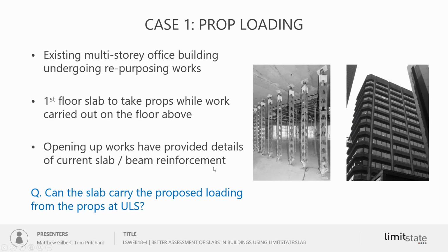So for the first case, we're looking at prop loading in an existing multi-storey office building which is undergoing some repurposing work, so of the type that you can see here on the right hand side. The first floor slab is to take some props while work is being carried out on the floor above, and opening up works have provided some details of the current slab and beam reinforcement so we can use them within the software. And the question that we want to ask ourselves is, can the slab carry the proposed loading from the props at the ultimate limit state?